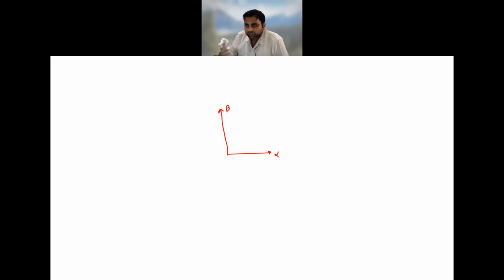That's when any space vector which is there, we can represent just by alpha component and beta component. We can represent the entire information about that particular space vector, Vs alpha and Vs beta, and then you can take the angle as tan inverse of Vs beta by Vs alpha. That will give you at what angle it is from the alpha axis.